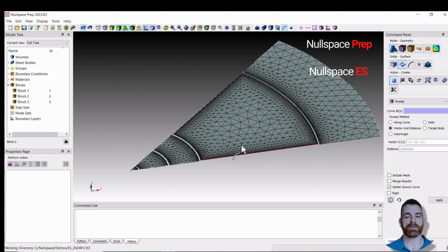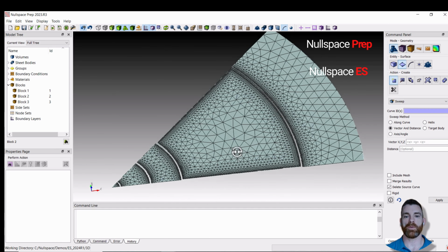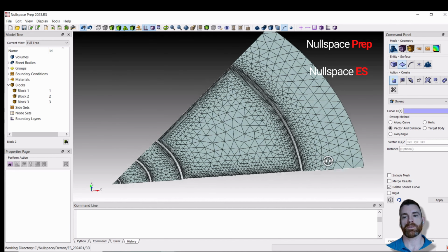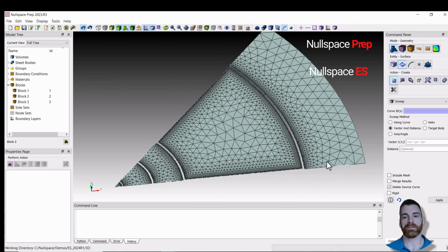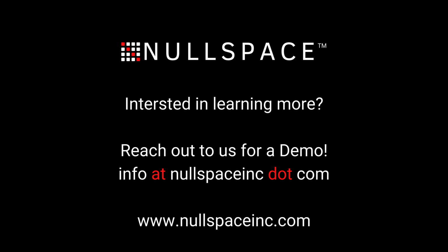Again, it depends on your application, and you need to have an understanding of how your electrodes are electrically tied together, etc., in terms of how best to exploit the symmetry feature. But if you can model and exploit geometric symmetry that is compatible with how your electrodes are wired up, and take advantage of even and odd symmetry, you can get a lot of computational gains from that.